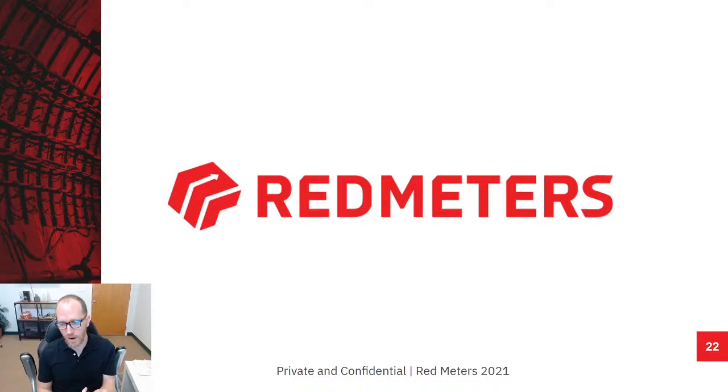So if you want to see specific gravity on one, and you want to see wear sensor on the other, or you want to see pressure on the other, you can change those. You can actually set the scaling as well. And you can put it in simulation mode, right? So you can say, if I want to configure this to my SCADA, I want to be able to send a specific amperage out and tell my SCADA, this is what we're seeing. Any electricians or electrical installers that are viewing this will know what I'm talking about. You can turn the red meter into simulation mode, just like you would when you're calibrating a flow meter or a pressure sensor.